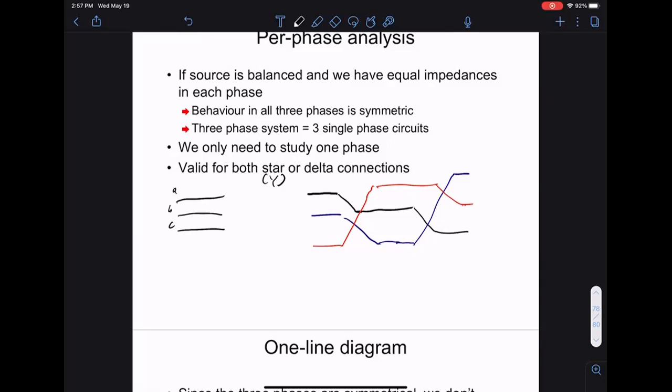Because they don't have the same inductance. If you don't transpose them, B sees fairly high inductance because you have 2 wires that are close to it, whereas A and C will see lower inductance because you have a wire that's far away. When you transpose them, it is true that the inductance for A may go up, but for B it goes down. So it's hard to say in total whether it goes up or down. It's more a rebalancing issue than whether the absolute number goes up or down.